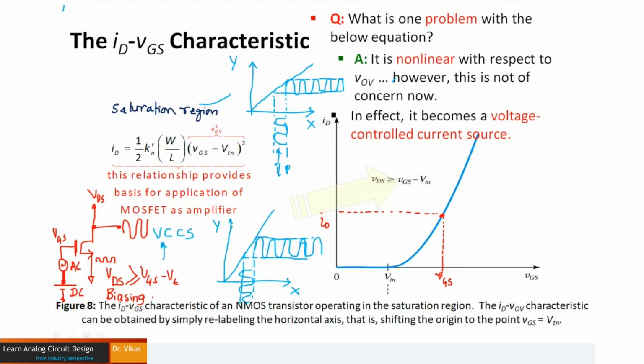And how do you get the voltage out of this entire thing? See, because the MOSFET here is basically a voltage controlled current source. Basically, the outcome of the MOSFET is the flow of current, which is the output. Current is basically the final outcome. But how do you convert that current into voltage? What I can do is simply attach a resistance over here.